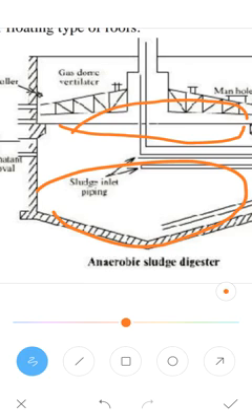In the standard rate digestion process, the digester contents are usually unheated and unmixed. The digestion period may vary from 30 days to 60 days. In the high rate digestion process, the digester contents are heated and completely mixed. The time required for digestion varies from around 10 to 20 days.